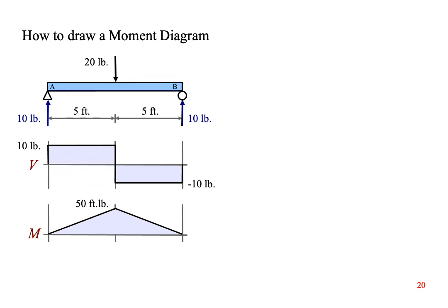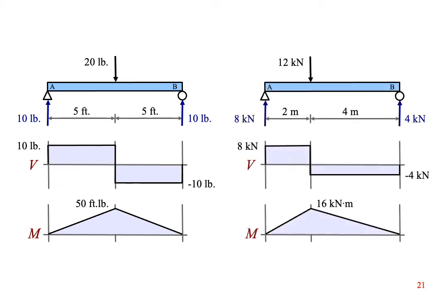You can draw a shear diagram using the wrong reaction forces, but you usually cannot draw a successful moment diagram if the reaction forces are wrong. This is a good thing because the answer tells you if you've made a mistake or not. There aren't a lot of engineering calculation methods that tell you if you've made a mistake. We'll review the rest of the shear diagrams and draw moment diagrams for each case.